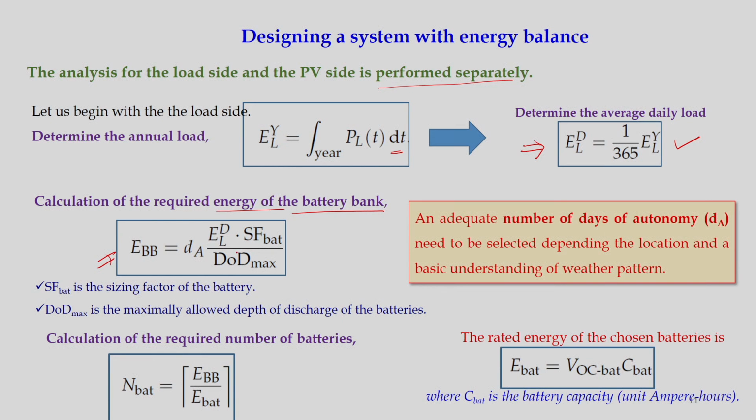Okay. And this SF is the charging factor of the battery. Normally its value is 1.1 or 1.2. Okay. And this DOD is depth of discharge. There is a maximum depth of discharge we need to consider, and this can be evaluated using what we have already discussed.